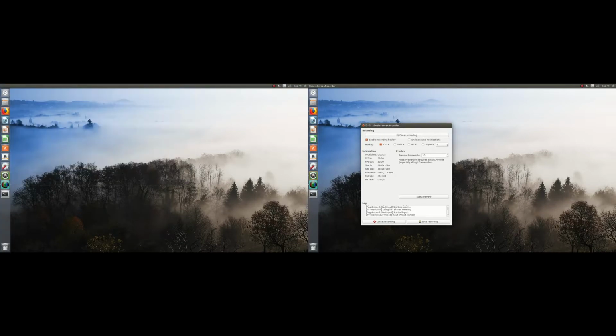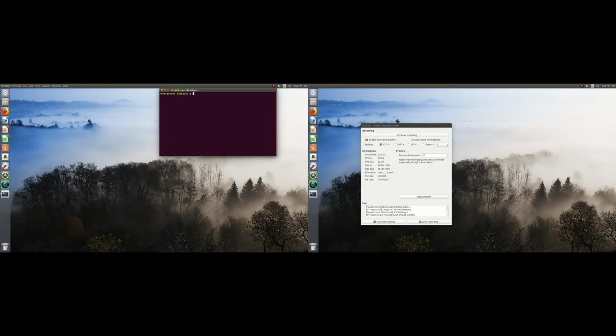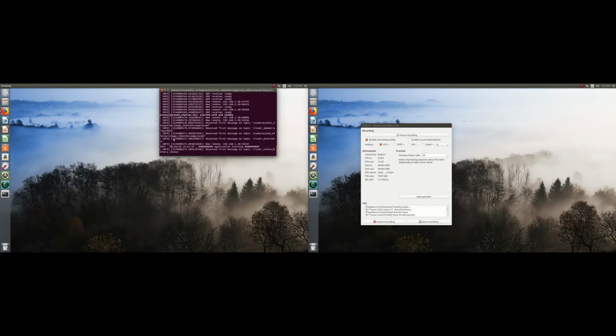To launch the software, you open a terminal and type roslaunch rover_main ground_station.launch, or hit up and hit enter on the most recently used one. When you launch it, it's going to start all the ROS nodes needed to connect to the rover and handle topic transports so that the ground station can send and receive information, and then it'll launch the GUI itself.